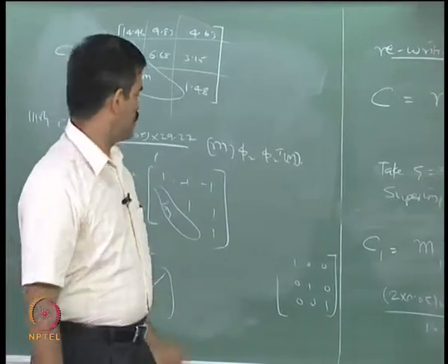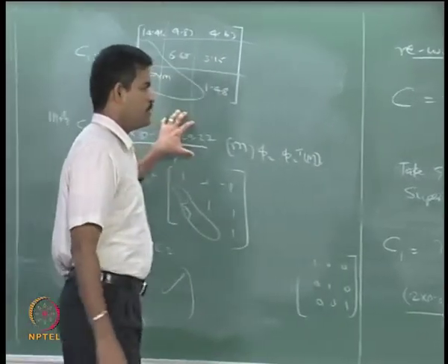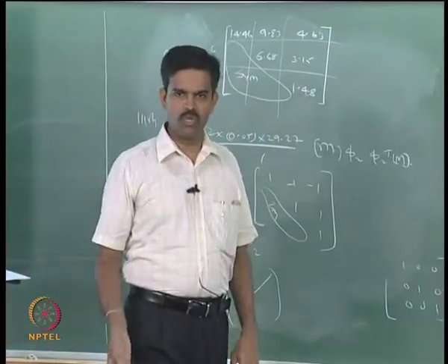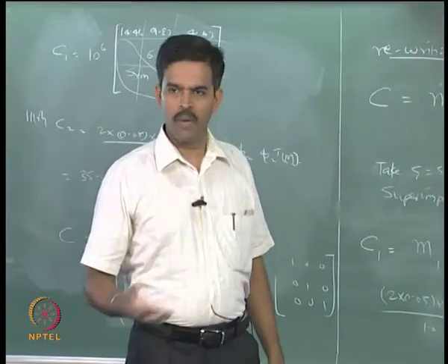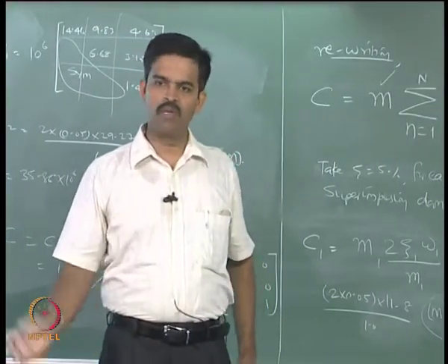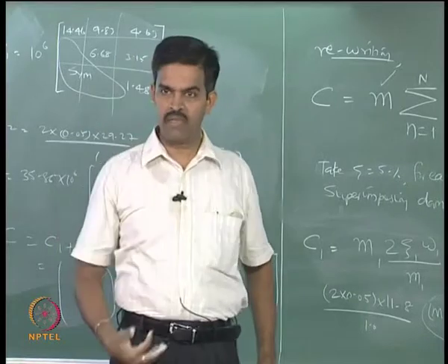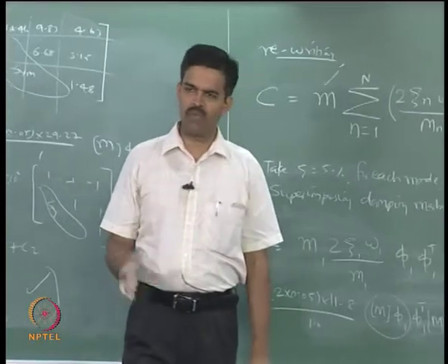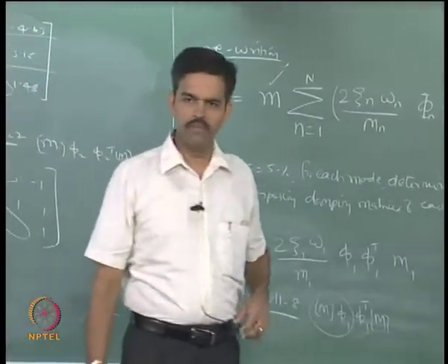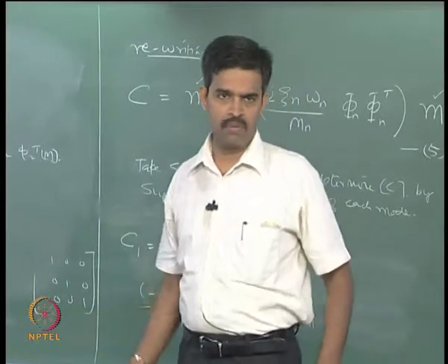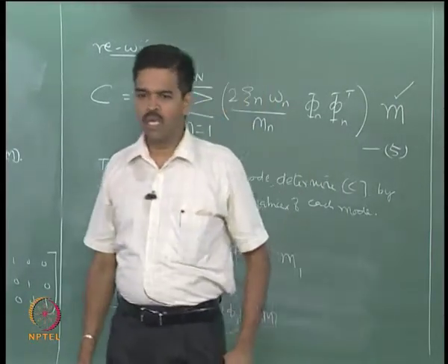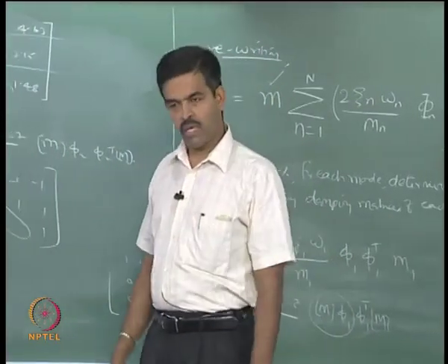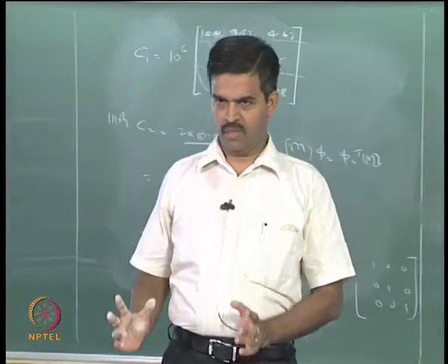Okay. So, this is an example application for the problem using this technique. Now, we have solved the same problem using 3 methods. You could also do it using the 4th and 5th method of C equals a0 M and a1 K, because you have M and K with you. You can always find all the 5 C matrices and could compare them and see how they are happening. One commonness between all of them is C will always remain as symmetric matrix. Okay. In this example, but not necessarily it will be symmetric, it depends upon the K and M matrices, right. So, in this example all were symmetric matrix, all were square, all were full sized matrix. Okay. It is not banded.